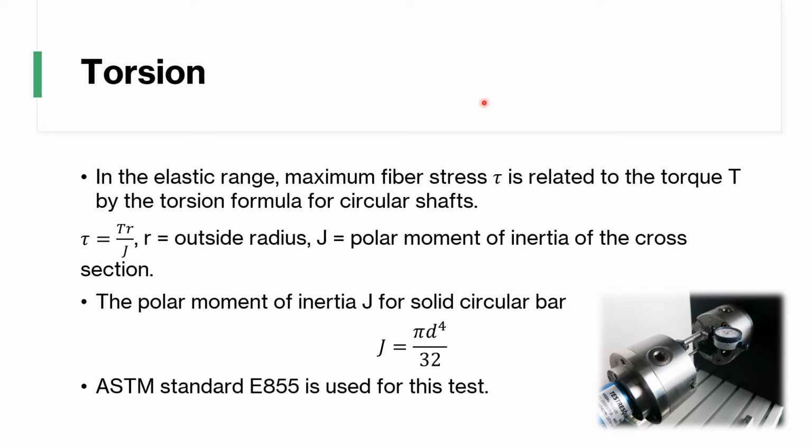That is a physics torque. It's a little bit different. Here we call this stress. So stress is related to your torque. Here we're using it with big T. So torque times R divided by J.